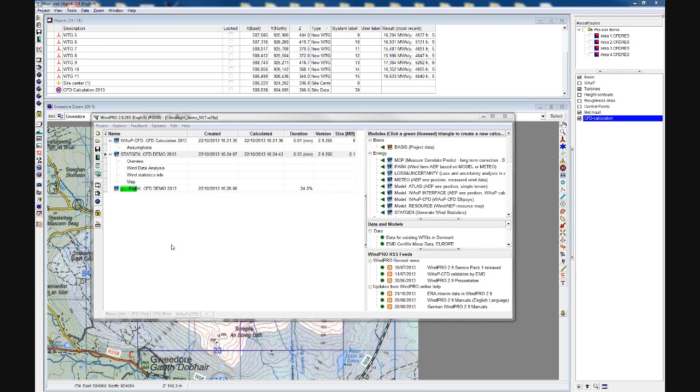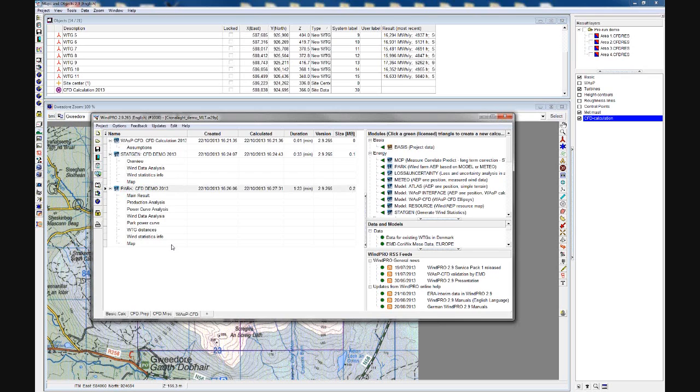But we have added a nice little feature in the line object where you can press the extend button, and then you can easily extend your existing local height contour lines with SRTM data. This will take you about a minute or so to extend your local height contour lines with 5 kilometer or 10 kilometer of extra orography from the SRTM shuttle radar topographical mission data.